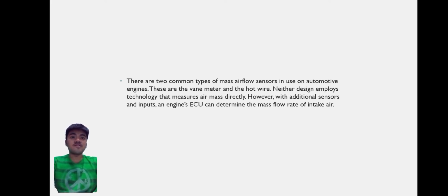When a MAF sensor is used in conjunction with an oxygen sensor, the engine's air-fuel ratio can be controlled very accurately. The MAF sensor provides the open-loop controller with predicted airflow information, the measured airflow, to the ECU, and the oxygen sensor provides closed-loop feedback in order to make minor corrections to the predicted air mass. Also see manifold absolute pressure sensor. Since around 2012, some MAF sensors include a humidity sensor.